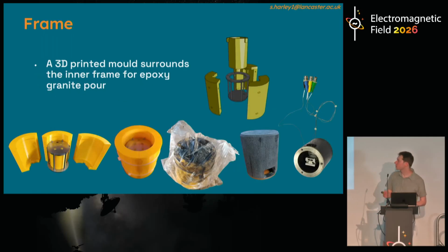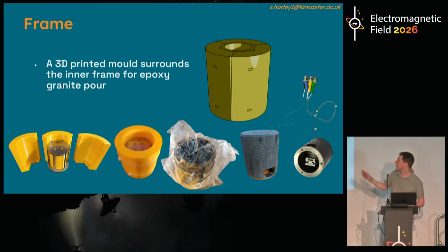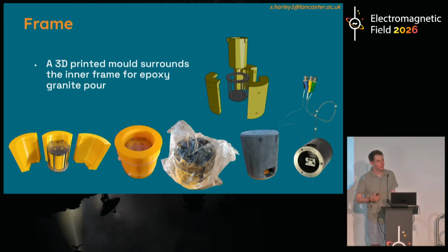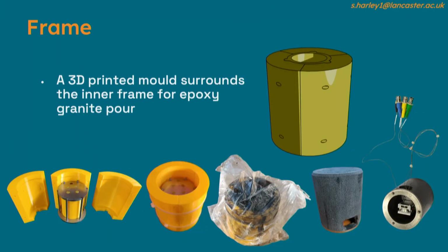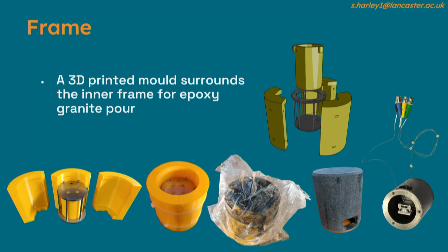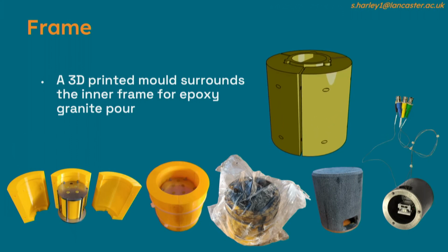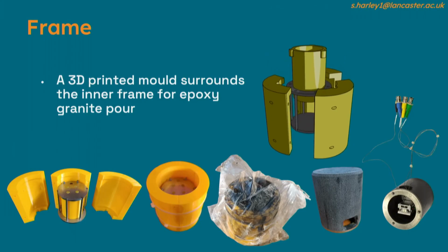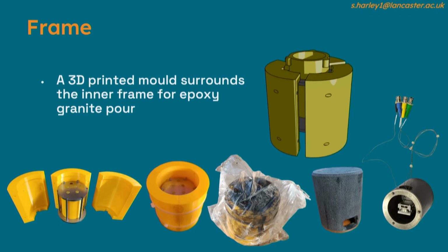So to deaden those resonances out, we made a 3D printed mold and we poured this cast epoxy granite composite, which is just epoxy compound with some granite aggregate, so essentially really coarse sand. And then after curing it and post-processing, we get our STM frame that looks like this. And in the center of the frame here, you can see the actual heart of the STM, which is the